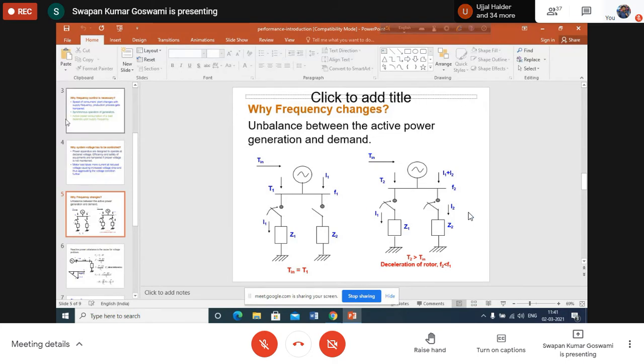Okay, actually your input system, basically what is the input system? That means the fuel control, water control, this system, they do not know that the load has increased. Because how will they know? Because loads are in the power system. In the power system, at a certain location, the consumers or customers have switched on their load. Obviously, the power station equipment cannot know this. So they will keep the opening of the turbine valve fixed at its previous value.